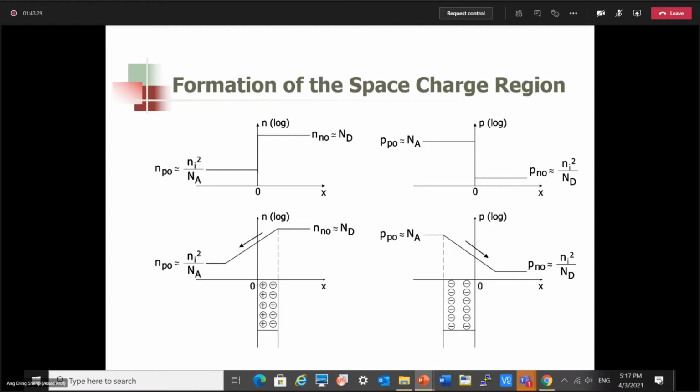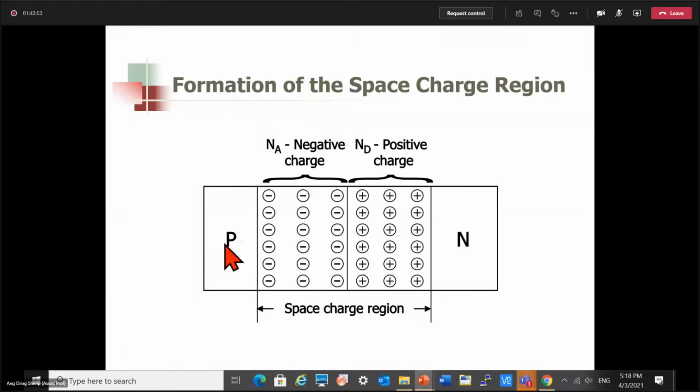The P-type semiconductor overall is neutral because the positive charges on the holes are compensated by the negative charges on the ionized acceptor impurity atoms. So in other words, this region where hole diffusion does not happen is neutral. So the net charge is 0, and therefore the net electric field in this region is 0. Okay, I understand now. Thanks, Prof.